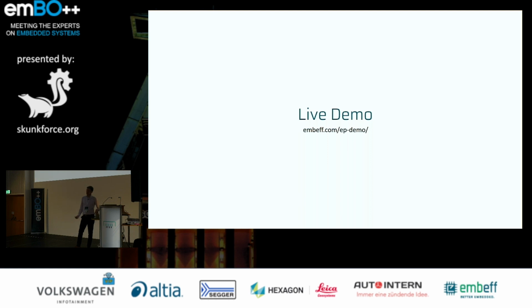That's a test system with specific microcontrollers inside. So there's a PCB inside with a microcontroller. In this box here, the STM32. And the box is able to access all the pins. Yeah, they are wired. And so we have access to all the pins. And what I wired here as well are some logic analyzer outputs. So the test system can basically route out all the microcontroller pins to some logic analyzer connection here so that we can understand a little bit better what is going on in the system.